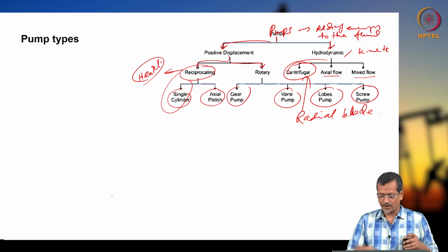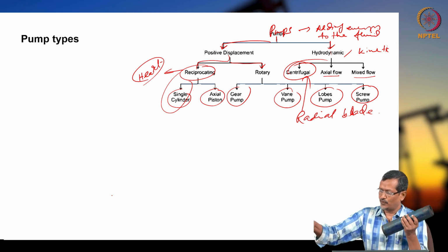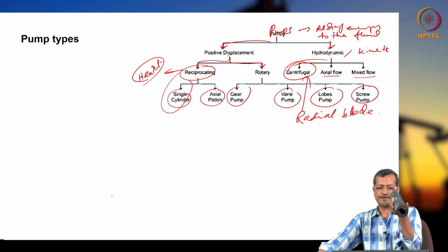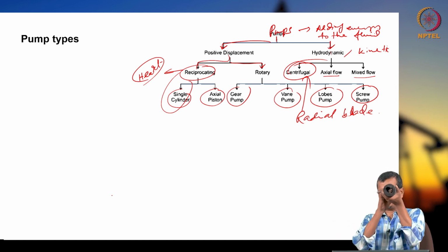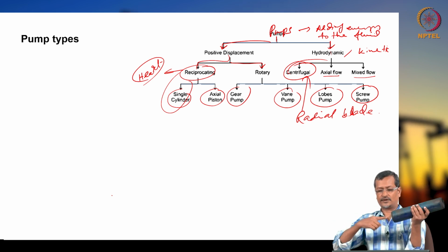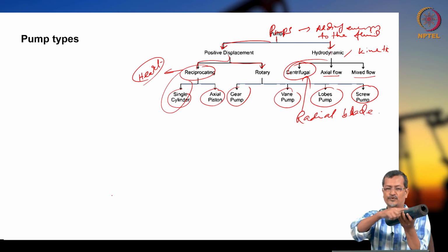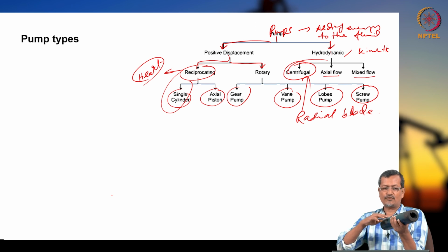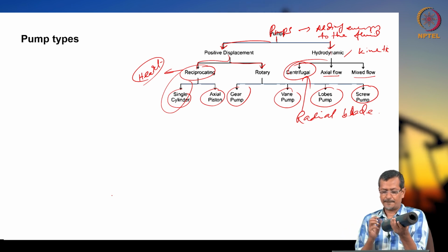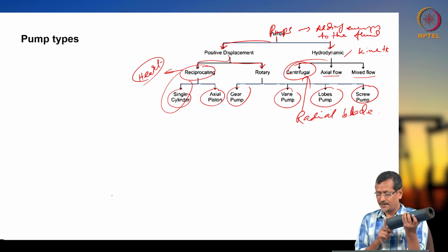So the whole rotor, this metallic rotor, will go inside this one, okay. You see inside a through hole is there, okay. This rotor will go through this hole, and if you rotate it, it will create a certain cavity and the cavity will be progressing slowly, okay. So it will be creating almost continuous flow, okay. But this is a very low speed pump.